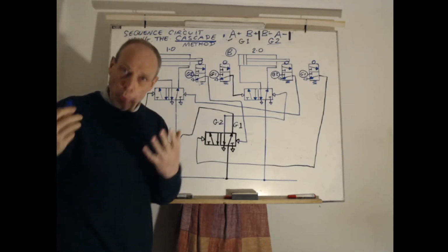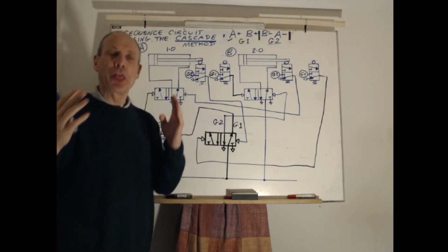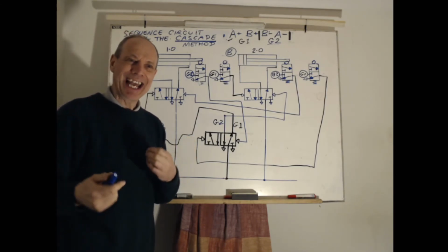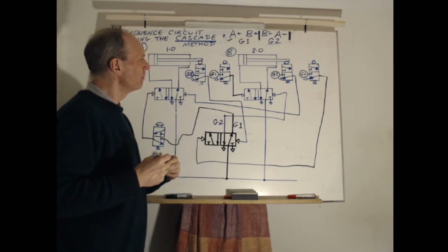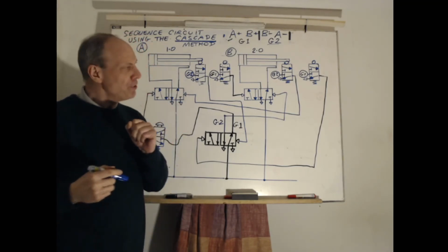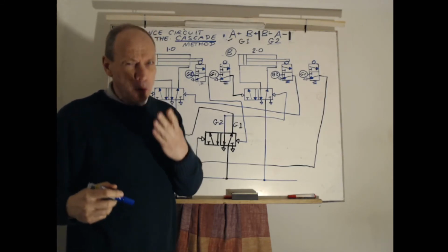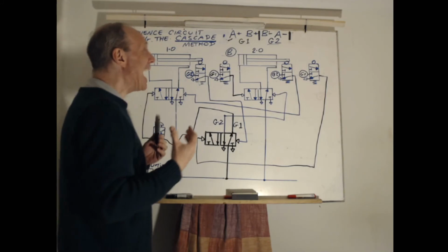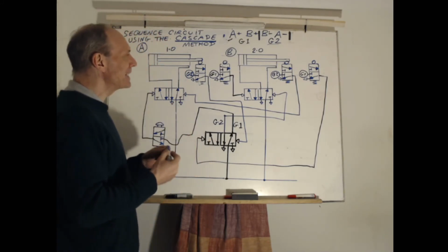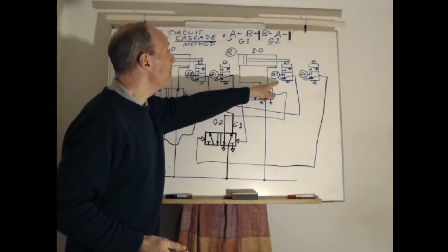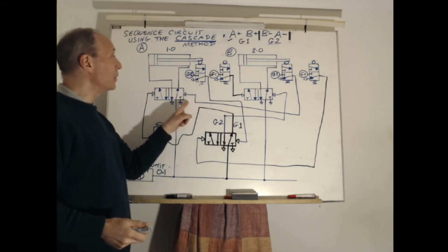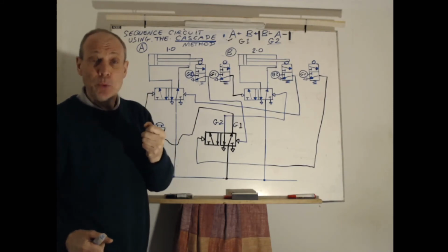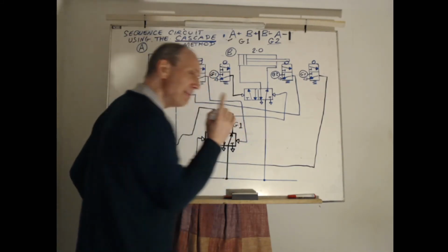On the next talk, what I want to do really is introduce 3 cylinders, and from those 3 cylinders, show you how to use the cascade within 3-cylinder movements. One other last point, and it's a point of interest and something that you are aware of, but as a gentle reminder to you really, if you wanted to delay an operation, for example when B goes B minus and then it signals to A minus, if you wanted a delay to be there for a few seconds, then you can use a simple method.